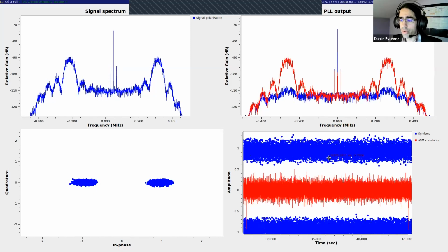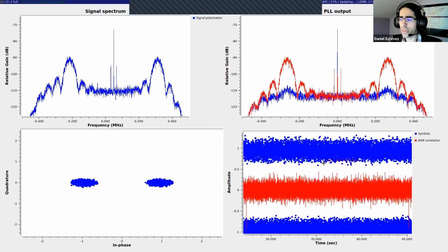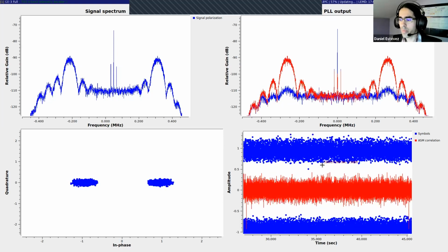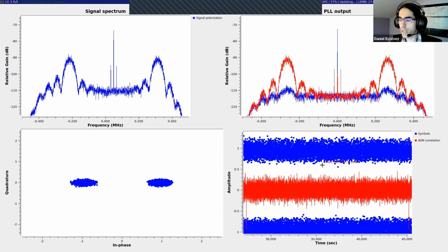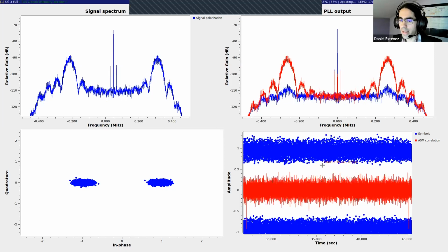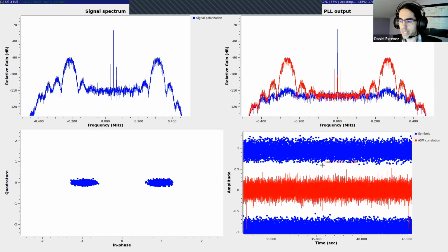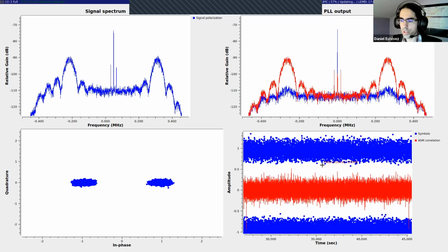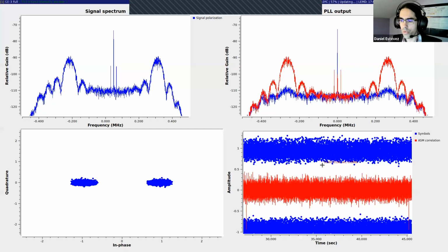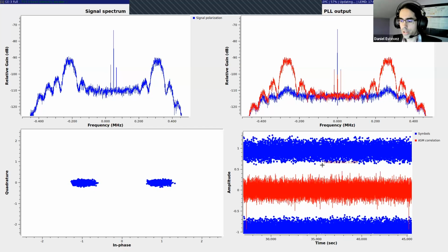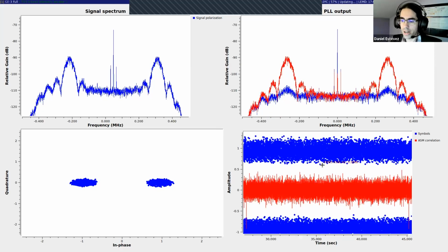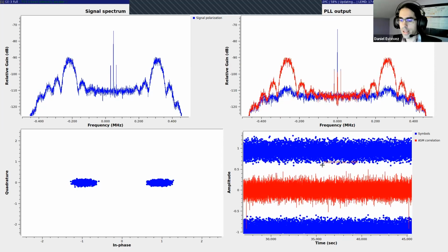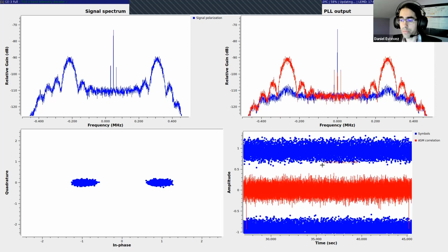And by the way, I don't think anyone has done this in Discord, but there's a shortcut. These can be skipped as well, because the error correction code is systematic. That means that the original message is enriched with more information rather than completely changed. So to the original message, more bits are added, and actually the same amount of bits are added.